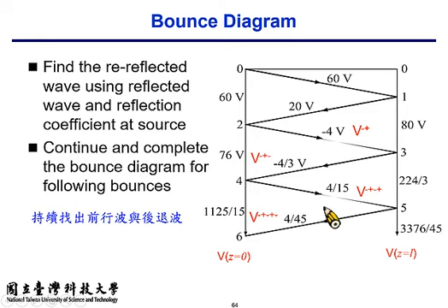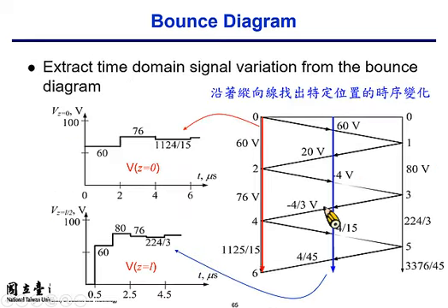Eventually, the total voltage signal and the total current signal on the transmission line will reach the so-called steady state. Although infinitely many higher-order, derived terms appear, they get smaller and smaller, and we can say it converges. Once it converges, the voltage and current you observe on the transmission line enter the steady state. This part is called the transient. After the signal converges, you enter the steady state, okay? Alright, so if you observe in this case, we observe the total